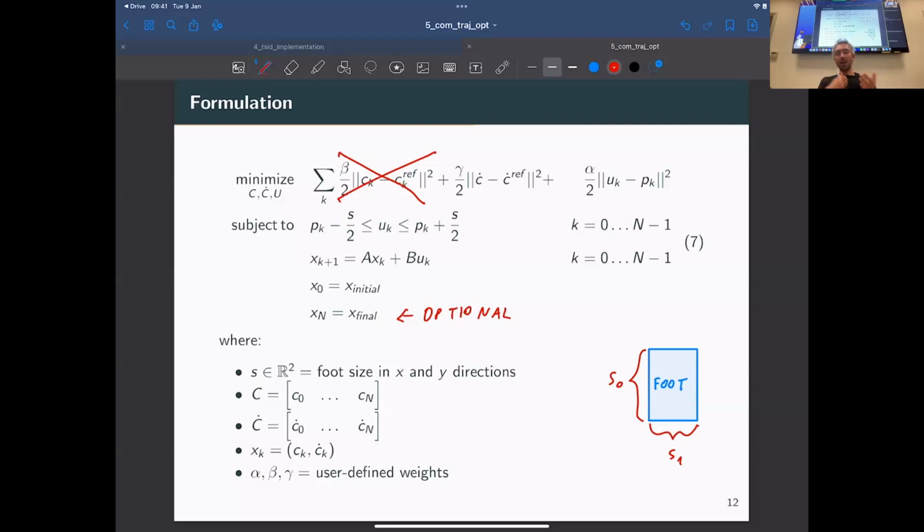I mean, you cannot do that either. It's hard maybe to estimate your own velocity, but trust me, when you walk, you don't have a constant velocity. Your velocity is constantly going up and down, up and down, because you cannot physically do that. So here we are moving from a rough desired velocity, which is not feasible, and if we gave that to TSID it wouldn't work, to something that is indeed feasible and consistent with the physical limitations of the robot. So that's the reason why we need this trajectory optimization problem.